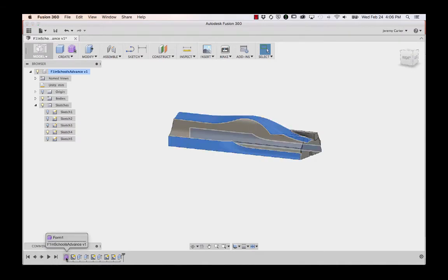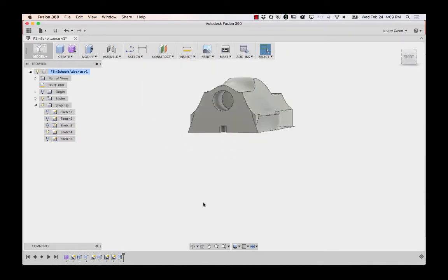You can also cut away by creating a sketch on the backplane. Remember, you can always go back to the T-splines and edit at any time. Be aware that using this method, you can produce shapes that will not always fit inside the main block. Remember to check the rules and regulations by using the sketching techniques described in the intermediate tutorial.